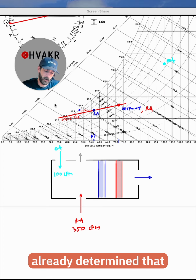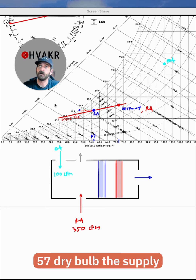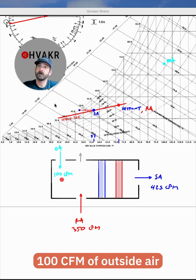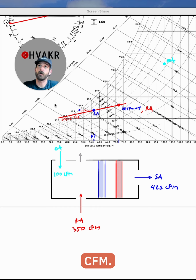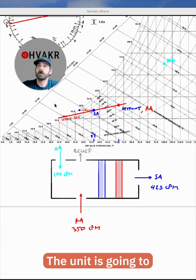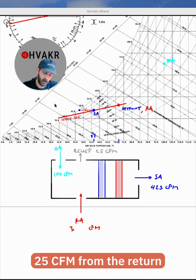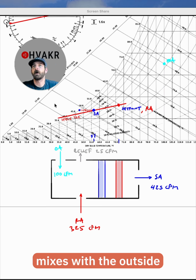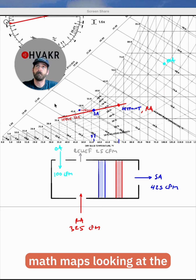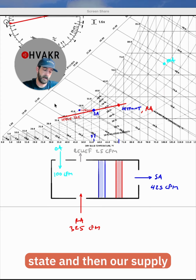Our supply air, we already determined. That was from part one of the series, and after recalculating at 57 dry bulb, the supply air CFM is 425. 100 CFM of outside air intake plus 350 of return yields 450 CFM. We only need 425, so we have a surplus of 25 CFM. The unit is going to relieve that 25 CFM. It's going to reject that 25 CFM from the return air before the return mixes with the outside air. That way we get the full amount of fresh air that is required. So this is how the airflow math maps looking at the unit here, and we've already plotted our outside air state, our return air state, and then our supply air state.